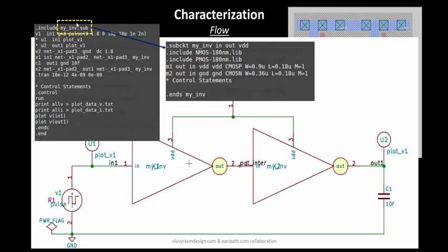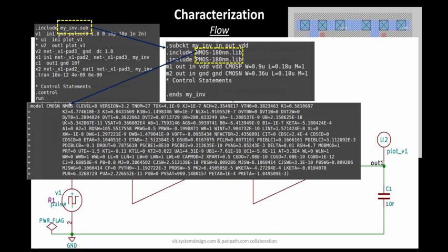So you have the subcircuits as well. Now in the subcircuits you have the spice model. So you have the NMOS spice models, and as I mentioned in my past videos, the spice models are nothing but the characteristics of the NMOS transistor. So you have the N channel behavior, or the N channel doping concentration over here. You have the VTHO.